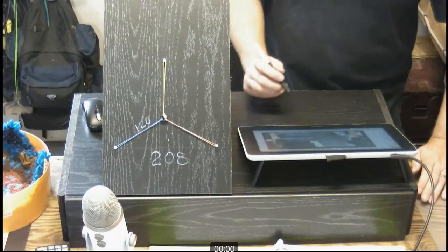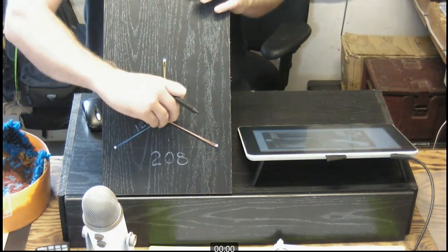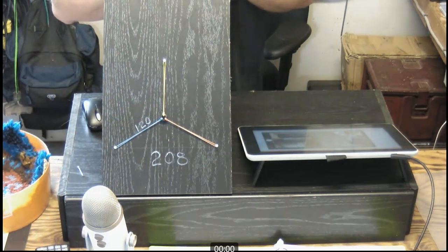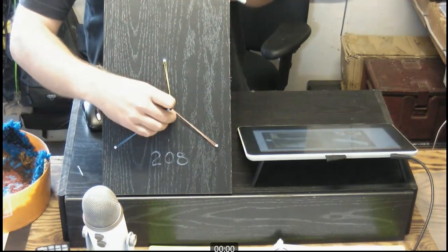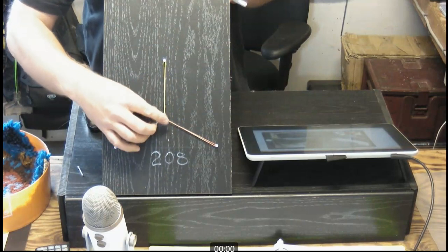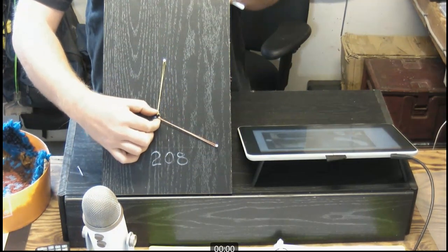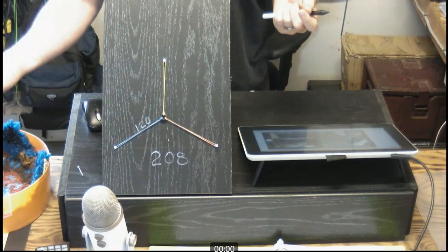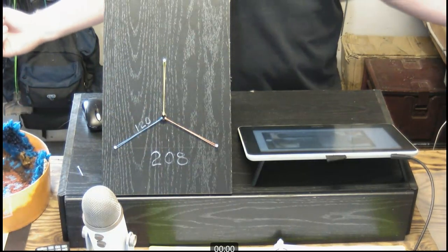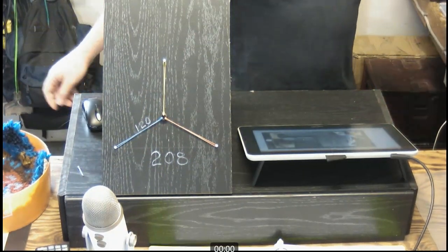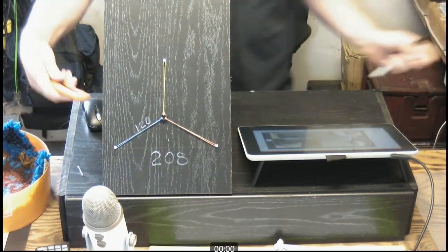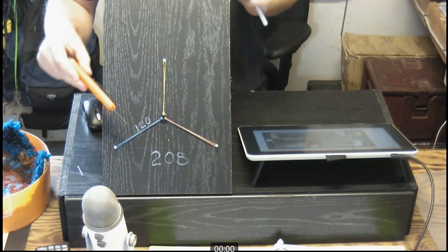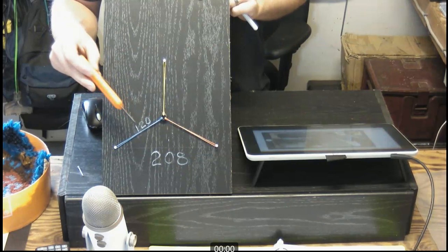Once again, let's go back to our demonstration board over here. Right here on the demonstration board, we've got that same system where we are working off of figure number 4 where we don't have the neutral connected to anything. So I can see that this thing can move around, but because I've got an equal value of voltage tension across equal loads, it's automatically going to center there in the middle. What we can do is open our load. Now, if you refer to your book over there, you're going to see that it's your load number 3 that is going to open.